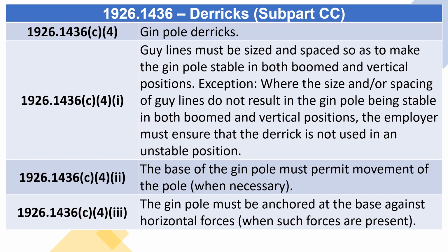The base of the gin pole must permit movement of the pole, when necessary. The gin pole must be anchored at the base against horizontal forces, when such forces are present.